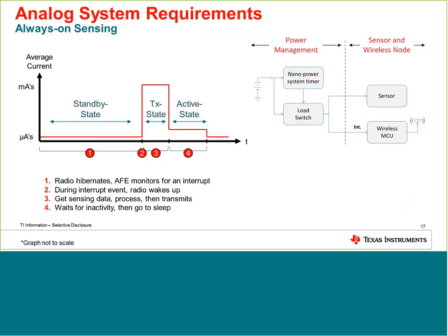So for the thermostat, we need to measure the temperature. And we normally measure temperature once per minute, let's say once per minute, because temperature is not going to change drastically in a range of milliseconds, or nothing is going to happen very quickly. There is a thermal inertia, and we really don't care what's happening between two measurements, because we know that the change can be very slow between these two measurements, every second, for example.